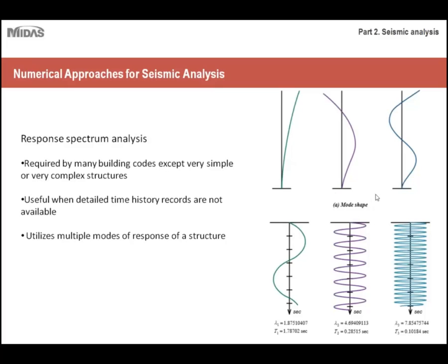As I said before, because seismic loading is cyclic, the forces acting on your structure will behave very differently. So it'll vary from second to second. What you'll do is take three critical modes and three critical conditions upon which the loads are acting upon your structure, and you'll perform the calculations for each one. As you can imagine, the displacement for this one would be completely opposite from this one. But both of these conditions are very realistic and very probable in the event of an earthquake.